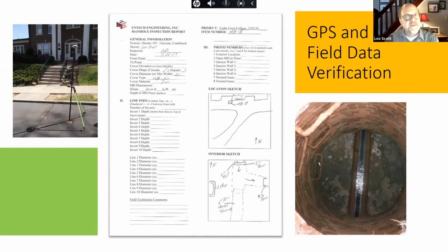And with certain items like manholes and inlet boxes, they filled out paper forms that provided information about the diameter or the dimensions of the items they found, and also brief sketches to record the location and the flow of water. And then finally, with every location they found, they took photo evidence of the items, either opening up a manhole or just simply taking a picture of a fire hydrant or a meter on a building.